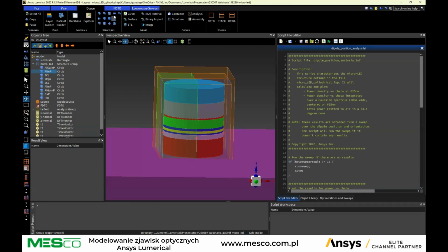Could be cylinders, rings, rectangles, or more complex elements. You also have the possibility to import data. In terms of import, it could be the layout, a GDS file. The interesting thing with importing GDS is that you can use this object here, the layer builder. Typically, we use that more in applications like photonic integrated circuits, where it's widely used.